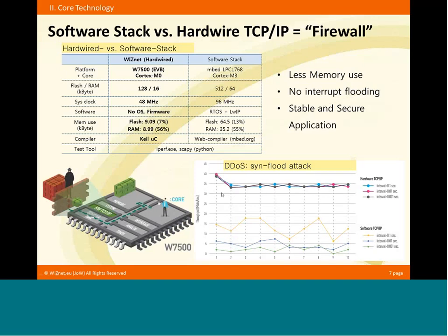This is just testing over time, and we flood the network with SYN packages and ARP packages and whatever. So kind of a distributed denial of service attack on our interface. If you do the same on a Cortex-M3, a medium-sized 32-bit core with 500K of flash and 64K of RAM, so that's a typical MCU you find for very small embedded applications.